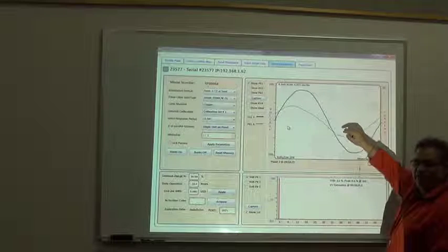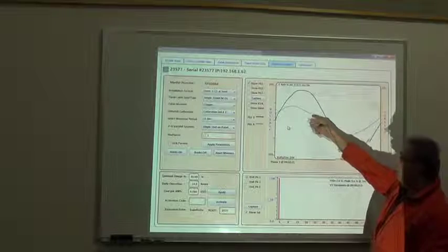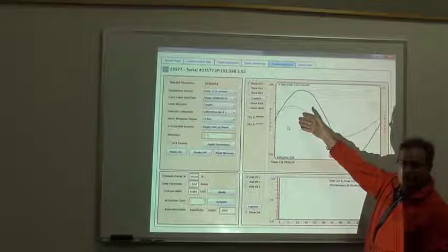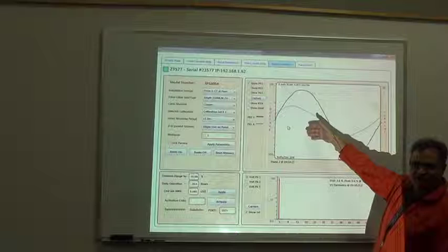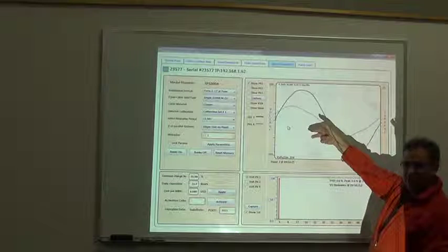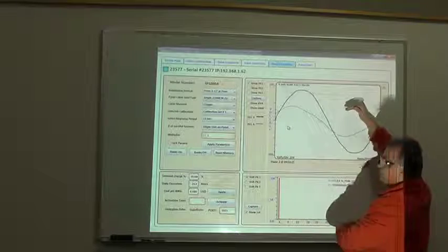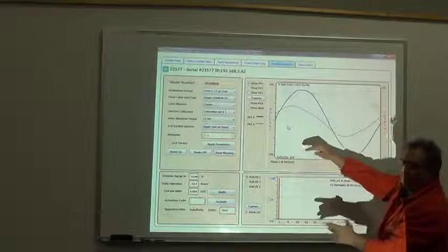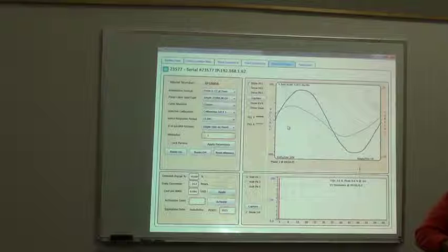We talked about that yesterday. It could either be lagging, or I can actually have the wrong CT. This CT may not belong to this phase. Also, if I have the wire reversed, this thing will literally go upside down, right? But when it goes upside down, it looks like it belongs to another phase.